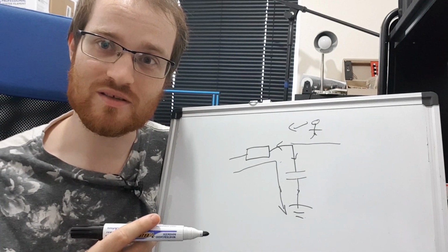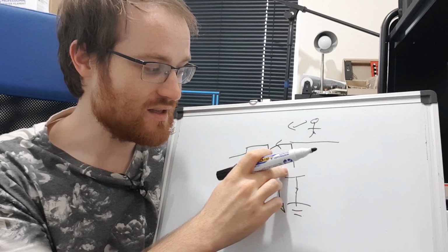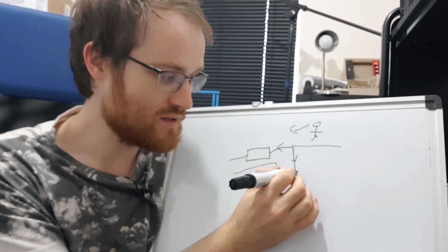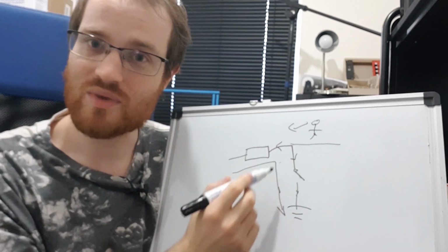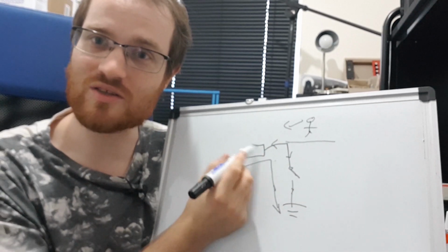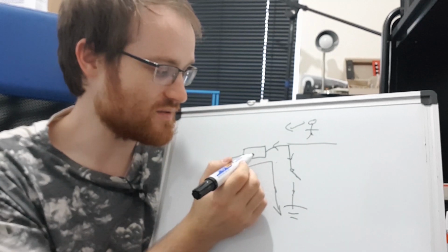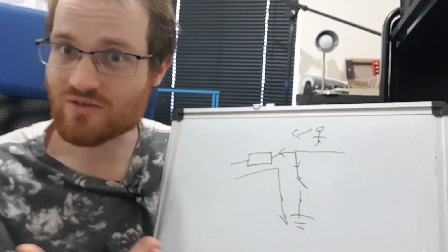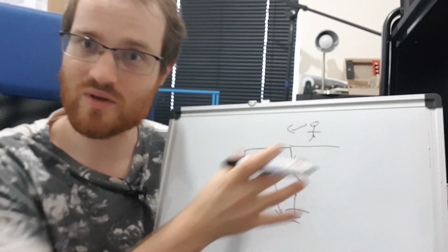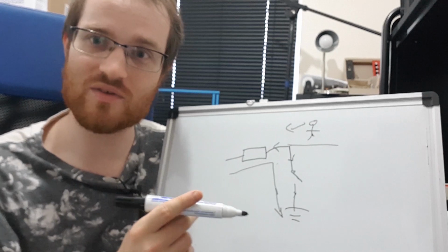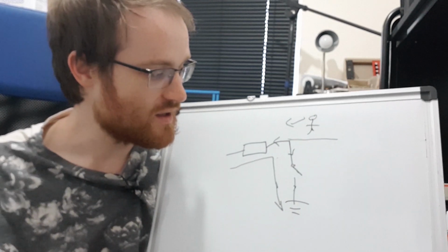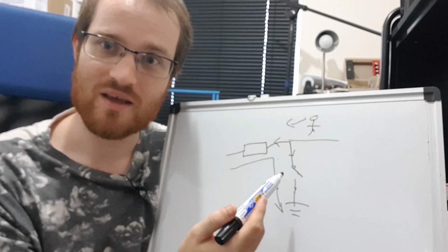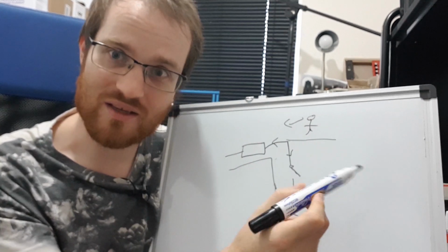Well, a parallel impedance is highest when this is an open circuit. When this is an open circuit, then this impedance doesn't shunt this impedance at all. So this impedance is just R, with no impedance to parallel; the parallel resistance would decrease the resistance of these two combined pairs. Again, go back and see my other video if you don't understand what I'm talking about. So at low frequencies, this presents an open circuit, and so our worst case output impedance is also R.